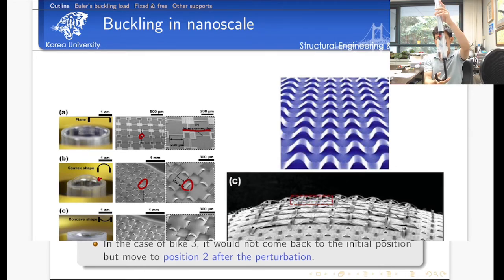Let's put a support on the bottom of this umbrella. The same gravity load, but to achieve an equilibrium, I have to pay attention to keep the equilibrium position. If I provide a small perturbation in the lateral direction, it is very easy to lose its stability, isn't it? It's an equilibrium, but an unstable equilibrium position.